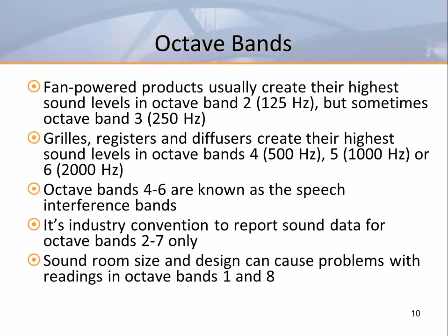Certain octave bands are critical to the overall performance of certain products. Fan-powered products, including fan boxes, room fan coils, and air handlers, typically create their highest sound levels in the second octave band, occasionally shifting to the third octave band as fan speed increases.